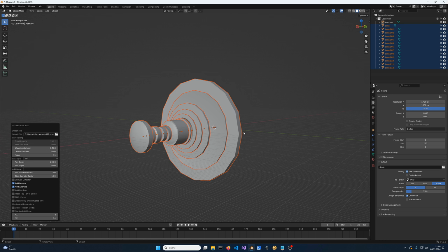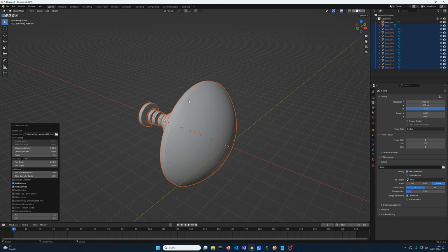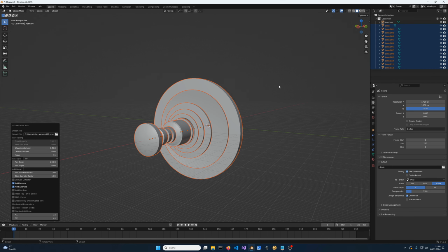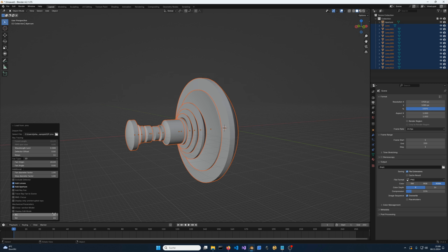You can clearly see the segmentation on the outer edges of particularly the big lens in this case, and that is not so surprising because by default the resolution parameters here in radial and angular direction are 8 and 16. In comparison, for the normal lens feature of OptiCore, where you only generate a single lens at the time, the default values are 32 and 64, so significantly higher in resolution. If I just add these, then you can see that now the mesh looks pretty smooth, barely visible in this view that the edges are still segmented.